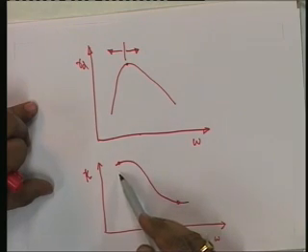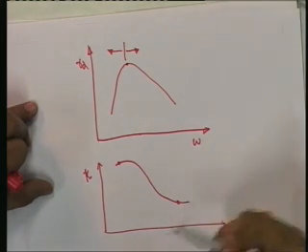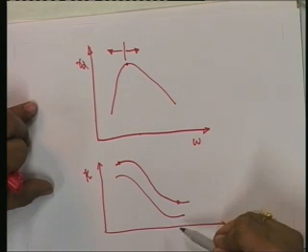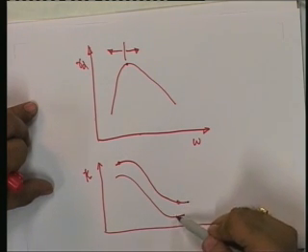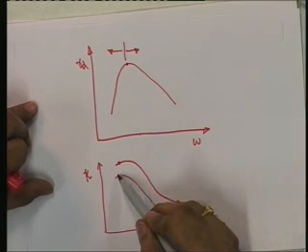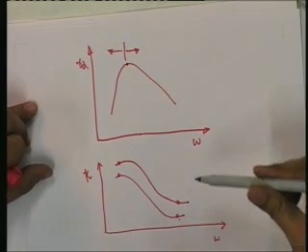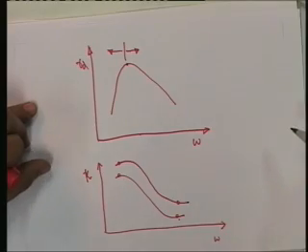Similarly, if I take this for a modified compaction, with a, this is for say a standard Proctor compaction. With a modified compaction, it can have a value slightly less compared to this standard Proctor compaction. So, the increase in compactive effort decreases the coefficient of permeability. Here again we connect back to the type of the soil structure which is prevailing in that moist compacted state for a given soil.